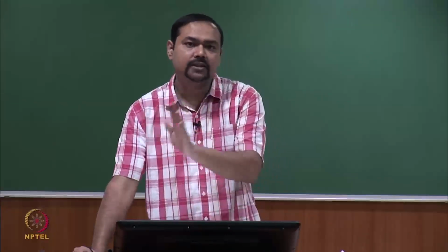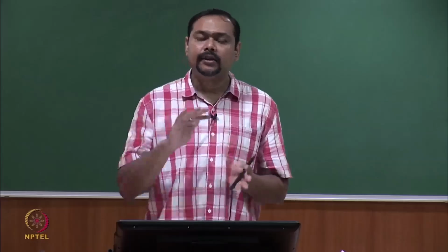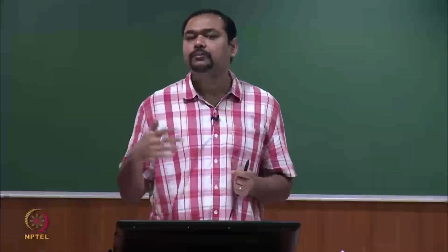So far we were talking only from the voltage point of view, but you can conclude that as we change the point O, the power flow through each of these three phases gets changed. PAO, PBO, PCO, the power through A phase, B phase, C phase are getting changed because we are changing the position of O, and thereby VAO, VBO, VCO are changing. So, if one phase is giving more or giving less, you can redistribute, you can balance the power flow and do many things.